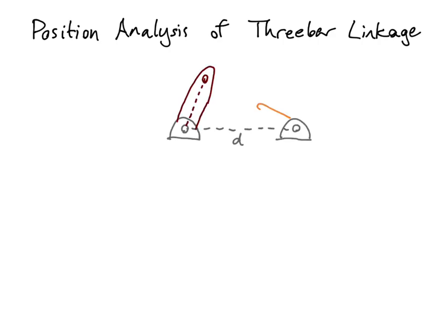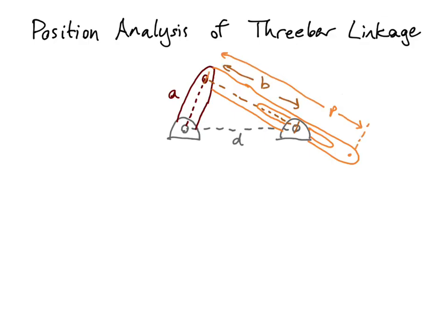So we're going to have our ground is still defined by D. We have that our crank is A. And then we're going to have a device called the slider. And so we could describe this linkage as having a crank, a slider, and a ground. So it's no longer the coupler and rocker because we only have a 3-bar linkage. We have a slider. And that slider is connected with a half joint.